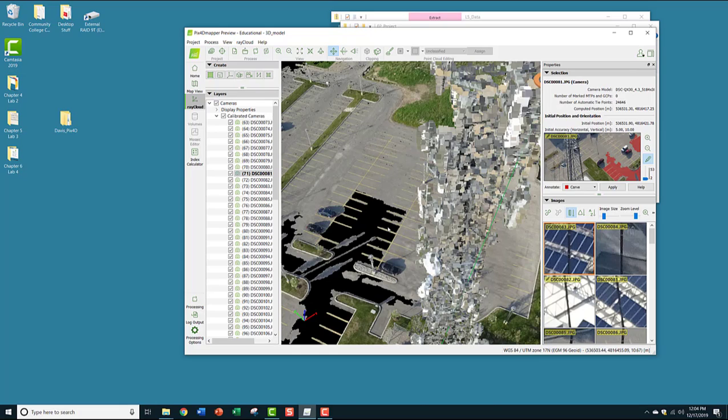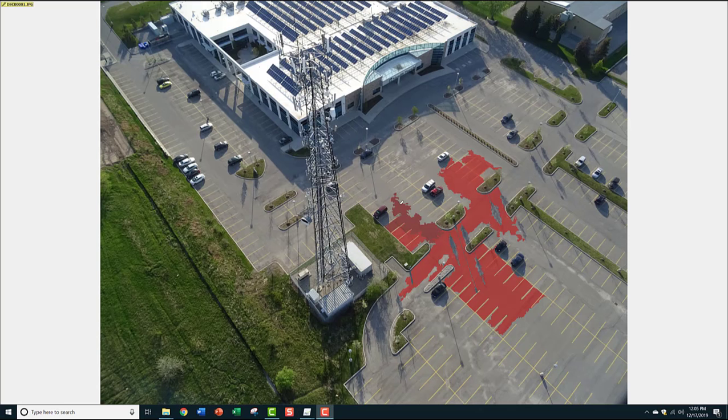The points are now removed from the DPC. Therefore, we consider this an advanced form of manual classification. And you can reference your manual as well. Now, if you highlighted pixels by mistake, you can unhighlight them by revisiting the annotation image. Hover your mouse over the highlighted chunk. Notice that your mouse symbol changes from a pencil, you see here, to an eraser. So you click and hold the eraser and let go, and it unhighlights them.